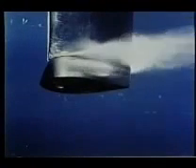Where cavitation is unavoidable, and conditions are such that supercavitating flow can be assured, it is possible to use supercavitating hydrofoil profiles specifically designed to achieve high lift-drag ratios.